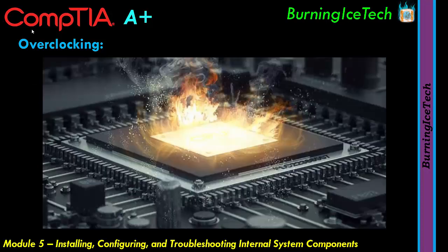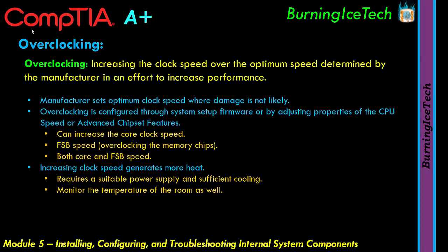Never mind the heat problem. Like we said earlier, if you're sending more power to a CPU, you're sending more heat to that CPU. So if you want to do that, you need to know what you're doing when it comes to cooling. The normal conventional heatsink and fan that you have on your CPU might no longer cut it. You might need to consider getting yourself a better fan, a better heatsink, or better yet, maybe liquid cooling.